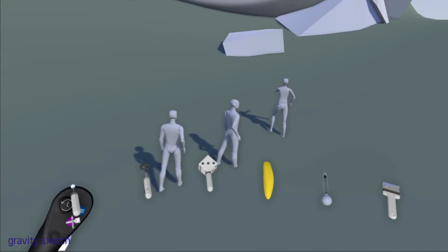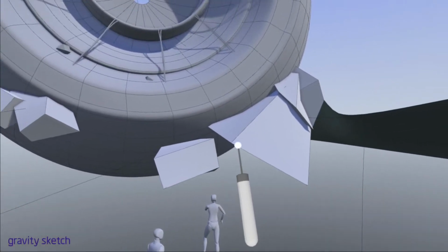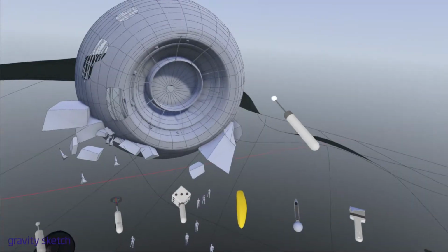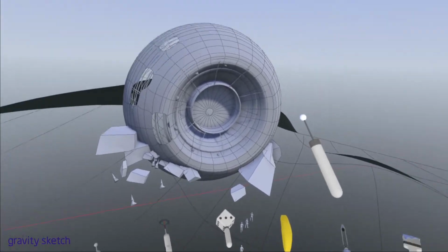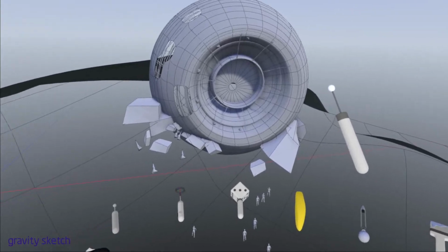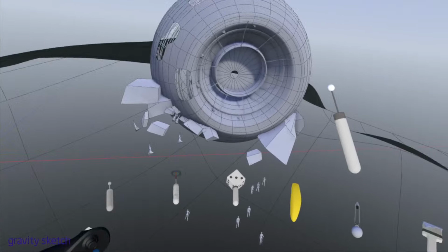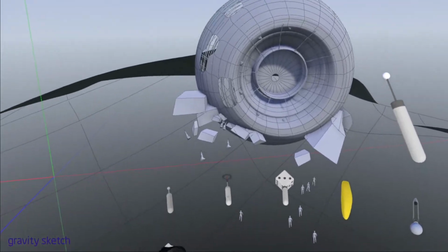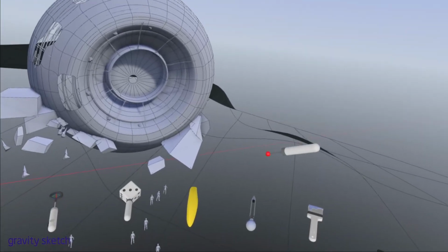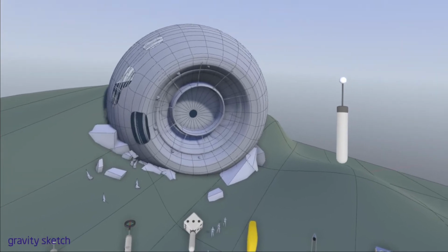So that's an update that we've given to the rotate tool. Many have asked what this tool does. Actually, a perfect example right now is reversing the normals. As you can see here, the normals on our sub D ground are reversed. This means when we import it into Blender or any other program, the normals are going to be all off. So we just take this tool, intersect it with the ground, click it, and now we have our normals on the correct side.